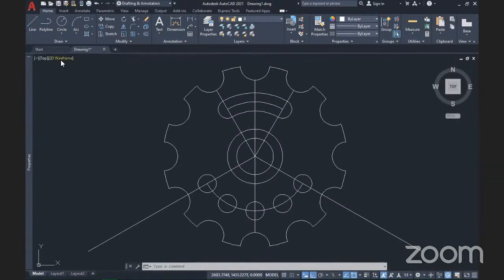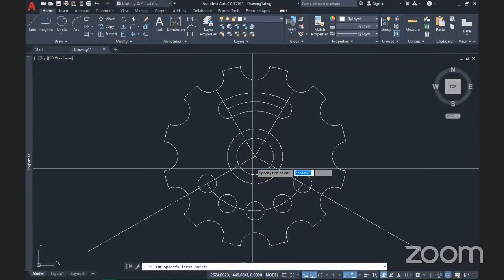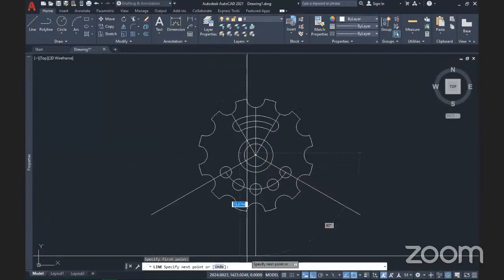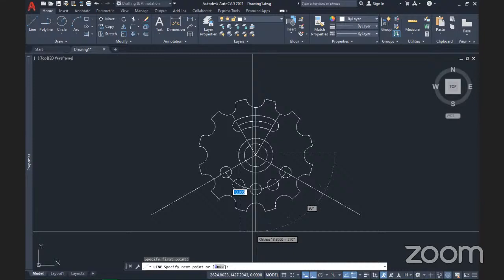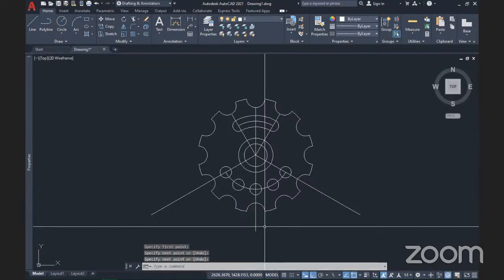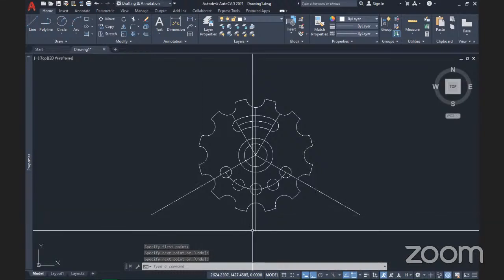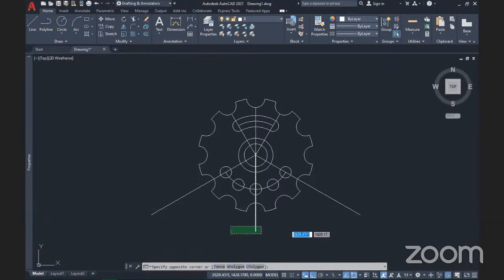Okay. I'll create a line of distance from this point there down to wherever I want. I can create it to infinity, but not infinity in this case. So then I will have to rotate this line to get what I want. So I highlight the line I want to rotate. I'll use my rotate command.